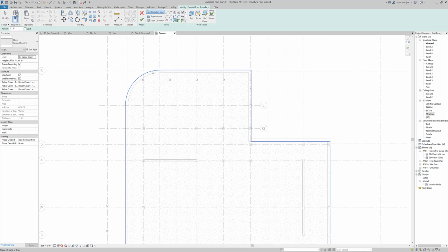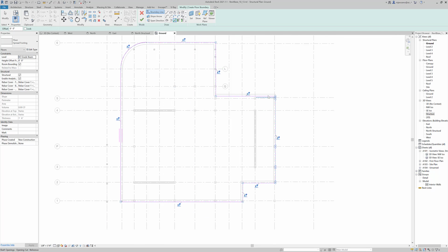So here you can see at the bottom of the screen, it's a chain, and if I move a little bit, this is the one I want. This is my foundation slab, and I'm going to click this, and now you can see that it just draws in that perimeter again. And again, this is why I recommend spending 5 minutes just going over everything, making sure it's well done, because we're starting to clone some of these elements so the mistakes will propagate.